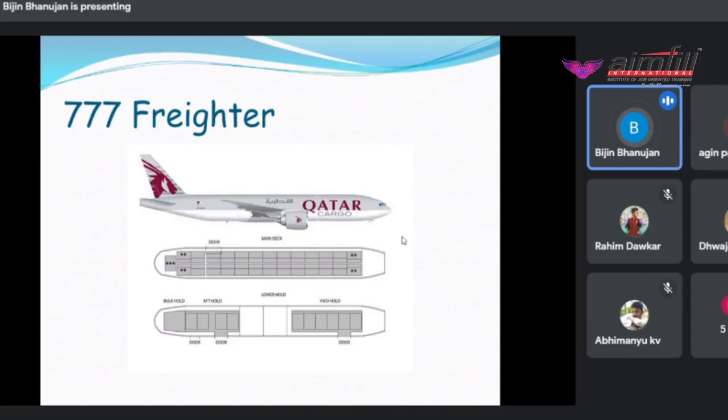So these containers have a code called AKE, in which A stands for standardized container. A means standardized container, that is, it's authorized and regulated by the government and IATA. So A stands for authorized container. K will be the base dimension of the container. In this case, for LD3, you will have a base dimension of 60.4 inches to 61.5 inches. So K stands for 60.4 by 61.5. That will be the base dimension.